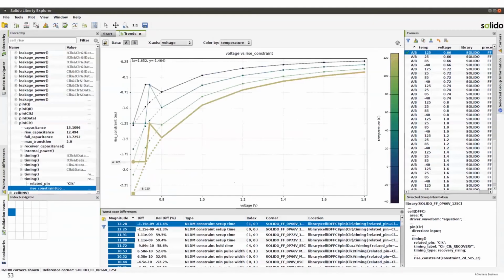Yeah, so for the people in the audience that have dealt with characterization before, timing characterization is actually really tough, because what causes these lumps here is usually an error in the simulator configuration, maybe you've got not accurate enough settings, or not enough time steps or something. A lot of the time it's a simulation error. So what you need to do is generate a SPICE net list, and then iterate and figure out, well, what went wrong there?